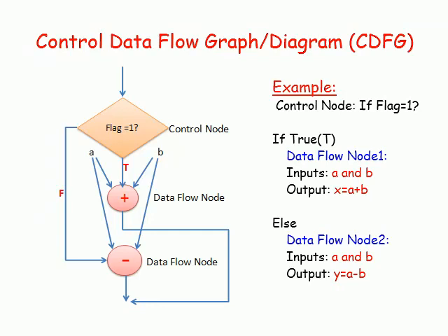The first example is capturing and saving an image to a particular format that is set by the user in a digital still camera, where everything is data driven, starting from the analog front end which converts the sensor generated analog signal into a digital signal, and the task which stores the data from the ADC to a frame buffer for the use of the media processor, which performs various operations like autocorrection, white balance adjusting, etc. The decision on which format the image is stored, formats like JPEG, TIFF, BMP, etc., is also controlled by camera settings configured by the user itself.